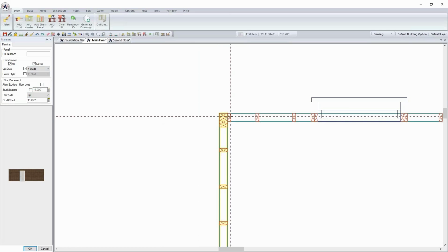Now that might sound trivial, but you add up the number of exterior corners in a given custom home, and you can see how you could quickly fall short in your bill of materials, even with a waste factor, if you're not accurately going in and making these modifications.